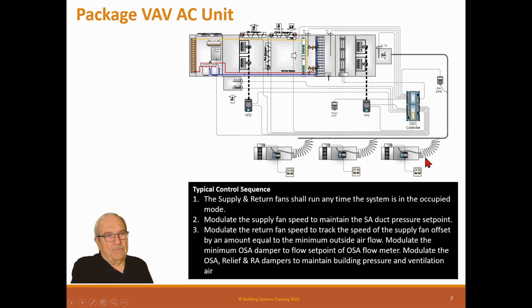Well, the way this is balanced, so you'll know, when we balance this, the balance contractor balanced these valves with them all at design flow, full flow. There's complexities here I won't go over, but anyway, it's here. And then we have a differential pressure sensor here, and it's going to speed this fan up or slow it down to always maintain that pressure set point. This pressure set point is established by the balance contractor to get enough air out of all these VAV boxes